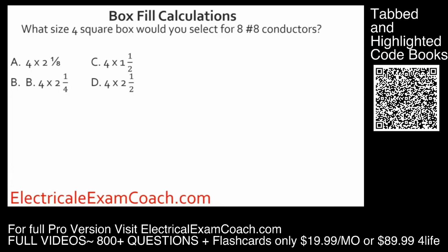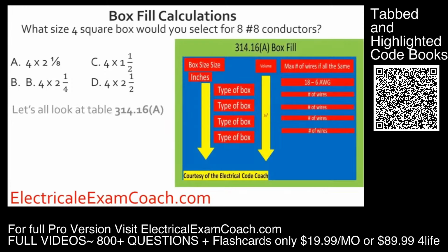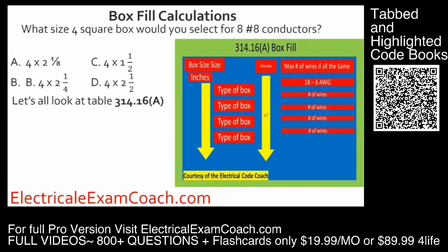What size 4-square box would you select for 8 number 8 conductors? We head to 314.16a. We're going to start here on the right hand side and we're going to find our size wire. Then we come down and make sure that we're in the right type of box. We cross over and we're going to find that it's A.